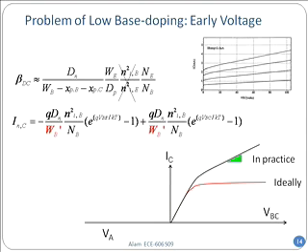In order to know how bad it is, ideal is if my slope is 0, that would be my ideal, right? If it is not ideal, then I want to know how bad it is. I can do it this way. I can say, how is the collector current changing as a function of VBC? That's the derivative, right? And the derivative is the slope. Now, the left-hand side is easy to see. Do you see the right-hand side of the equation, IC divided by VBC plus VA, in the following way?